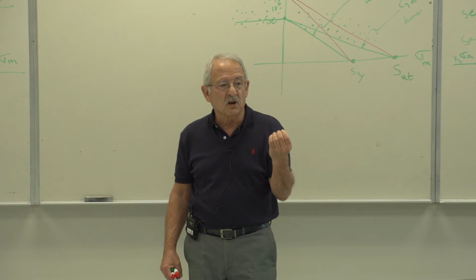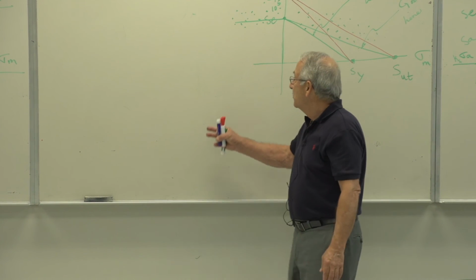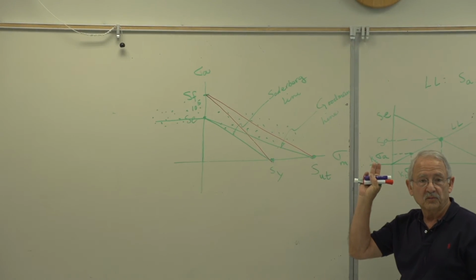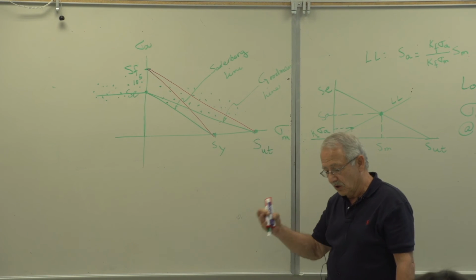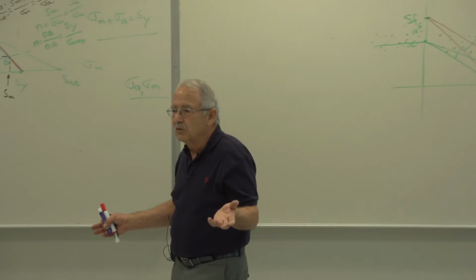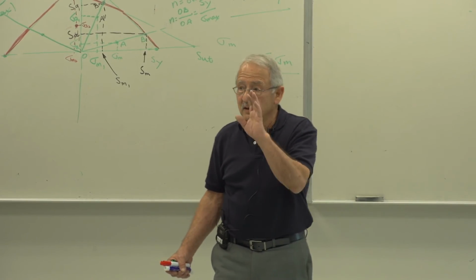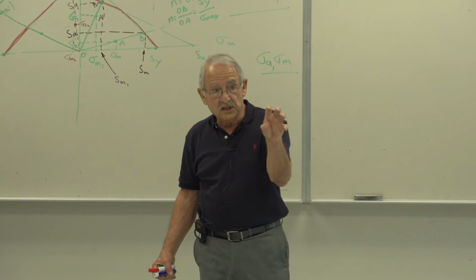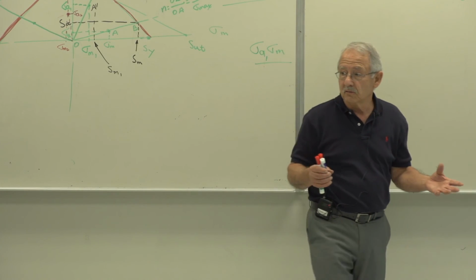In other words, no stress concentration. Otherwise, the same story happens there as well as here. So if you have those cases, in other words, polished and all of that, then you don't need to do anything. You don't even need to consider Sm, provided the value of sigma m, the mean stress, is less than the yield strength of the material. In other words, you're not yielding it right away.